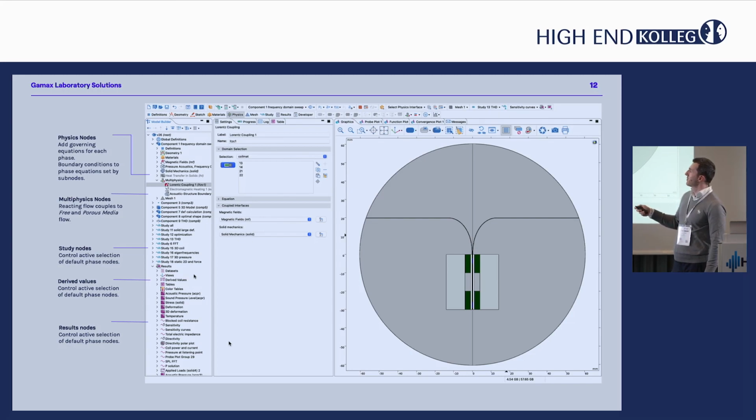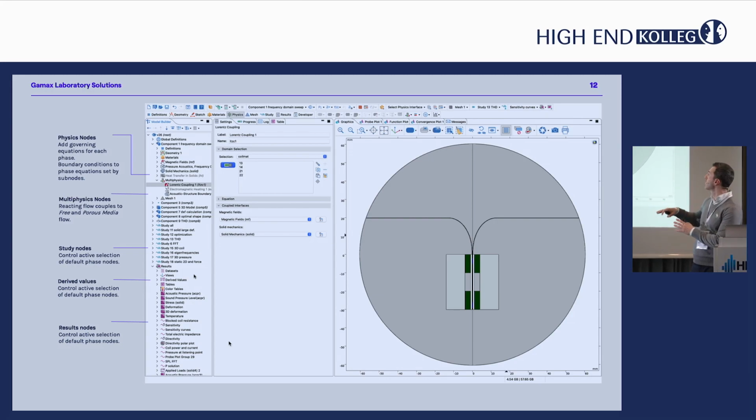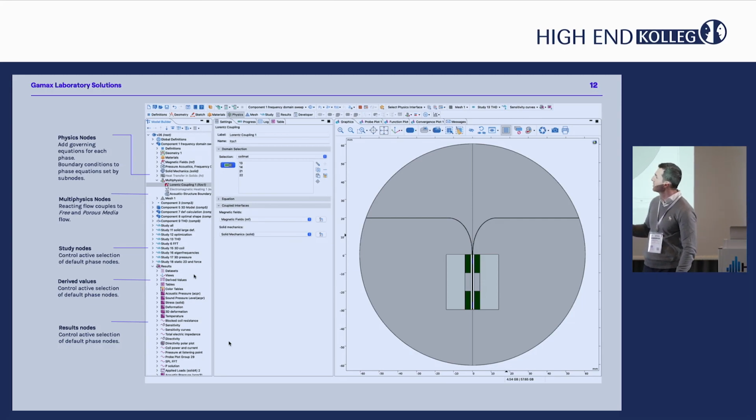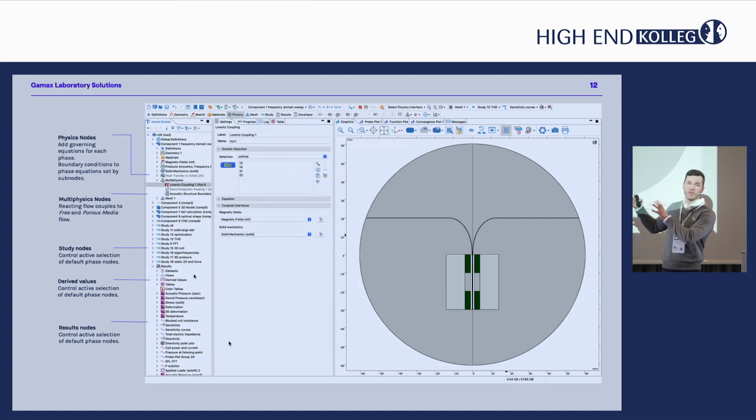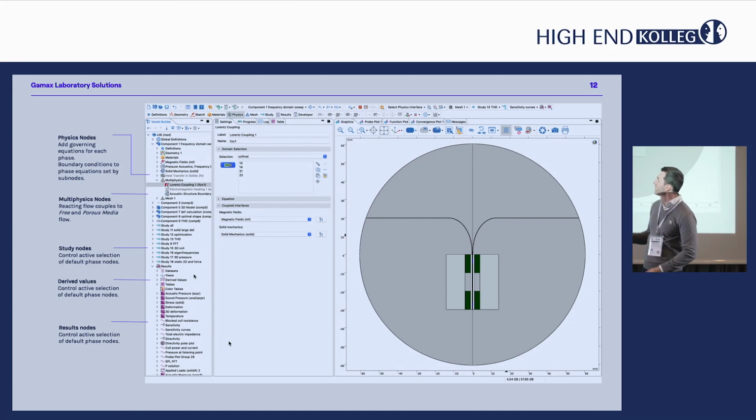And technically that's from the physics side. We have different study nodes for different calculations. So the study starts with calculating the bent shape for the membrane, and then we have the solution for that one. Then it creates the geometry, solves the problem, sets up the static magnetic field, so that will be used for the linearization point for the frequency domain study. And then we get all the relevant figures here, so that's handled automatically there.